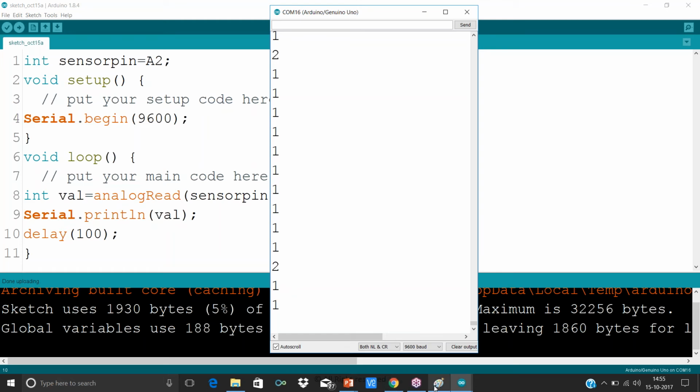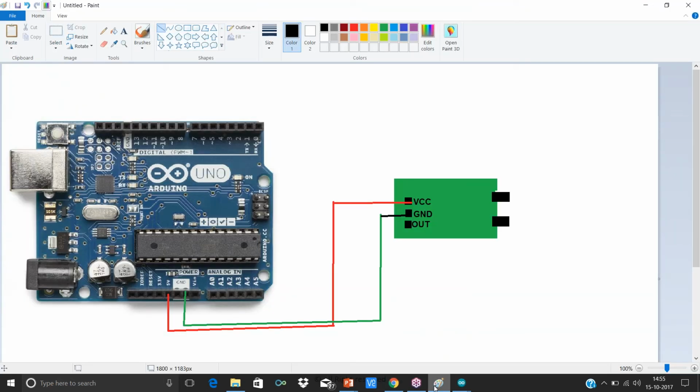Okay, great. I hope you could find the components, IR sensor and Arduino, out of the components of the kit. IR sensor, Arduino, and USB cable. Once you connect this USB cable to Arduino and my PC, the Arduino will be powered up, and then you need to take two simple wires. You will be able to find the two pins on the sensor, VCC and ground. The sensor will have three pins: VCC, ground, and output. So you need to find just two pins, VCC and ground.